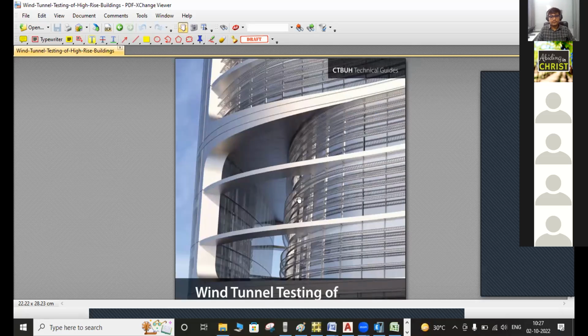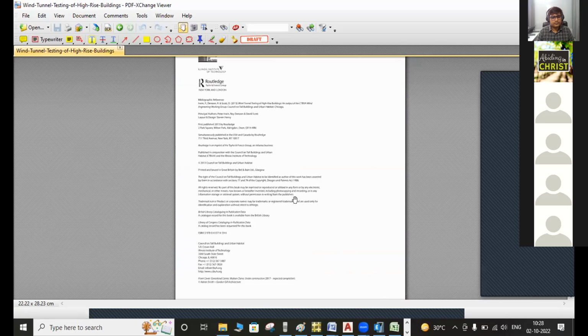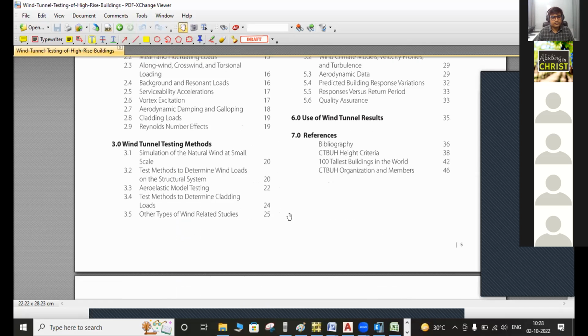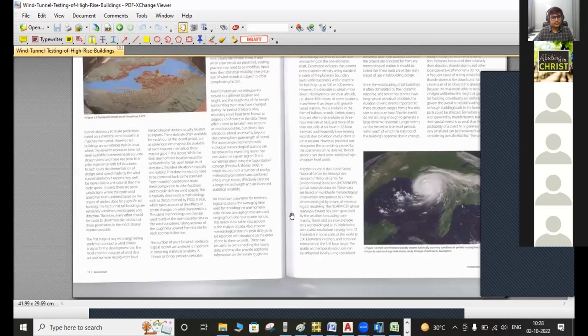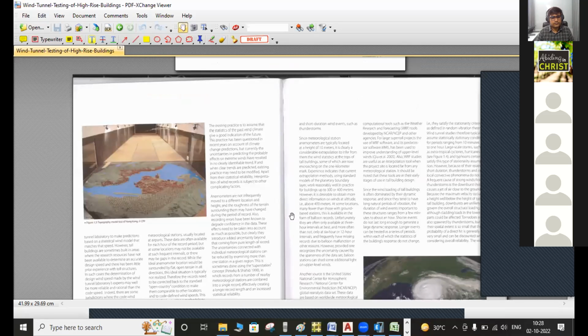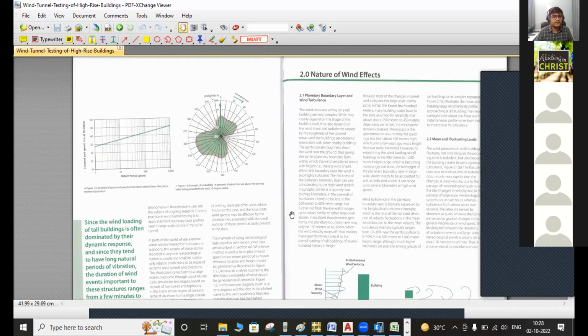So, sir, when we study the CTBH, this testing for high-rise buildings, or study ASCE 7-16, the test is performed in the workshop. In that part, we get our results by identifying the wind speeds, the geographical conditions, and the category of wind. This is the data input from the laboratory, right? Yes. For India, you can check this data on the meteorological website provided by the Government of India. There you can find this kind of data for wind speed, the current wind value.